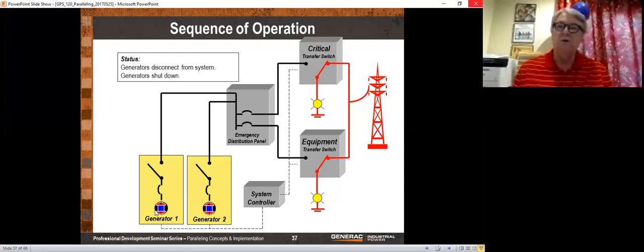If you want to, you can go out there and just start generator 1. You do that by turning the switch to manual. So there's auto, off, manual. You turn it to manual, boom, the generator starts, and then there's a little button on the screen that says manual mode parallel. You push that button. That's all that's necessary in order to parallel that generator to the system, and that's all that you can do. We don't let you go in and fix this thing.